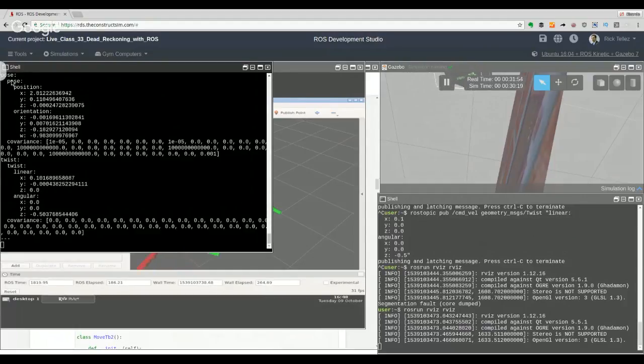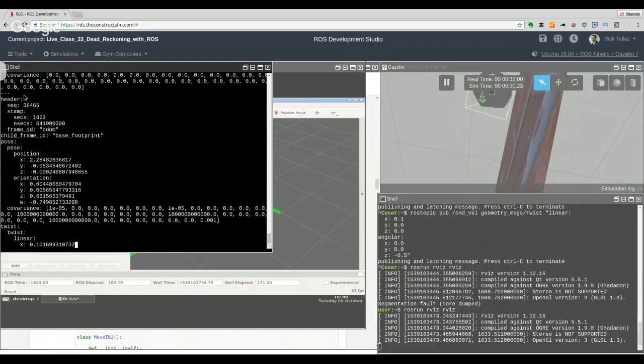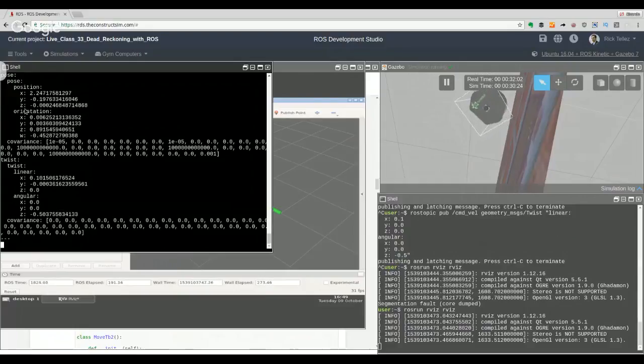And you can see here that we have the pose. This pose contains two parts: the position, that is the X and Y, and the orientation. The orientation of the odometry in ROS is provided as a quaternion. That is why it has 4 components. I'm not going to talk about quaternions here today. Just understand that this value of the orientation is the one that can provide us